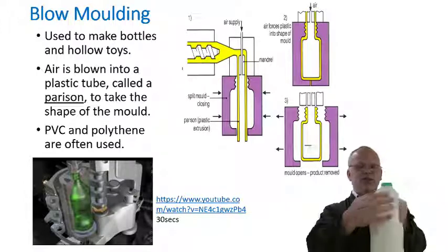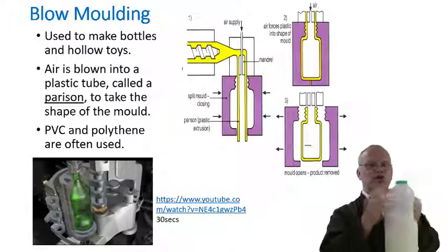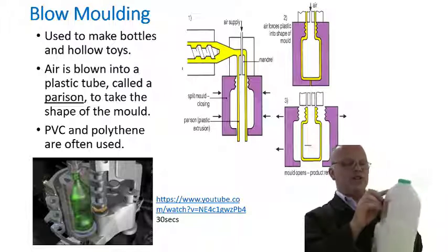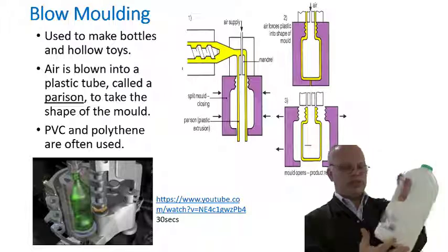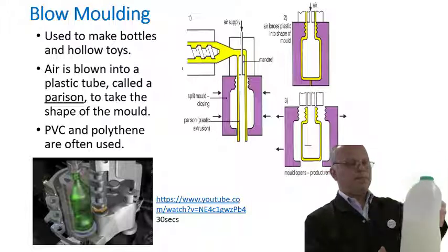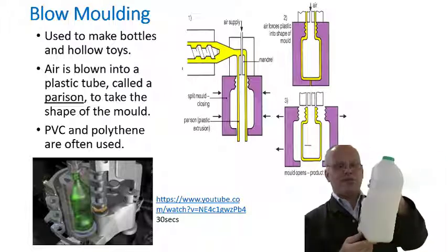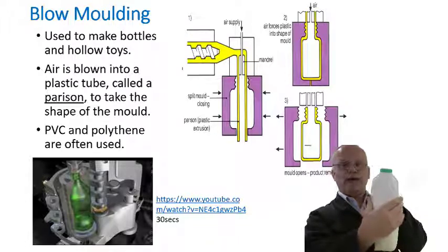Little bit of writing around it, it's not very clear. It's one of the reasons we wouldn't use blow moulding for really precise objects. It doesn't take up clear edges, it's better for soft rounded shapes. Okay, so this is high density polyethylene, very thin wall section.